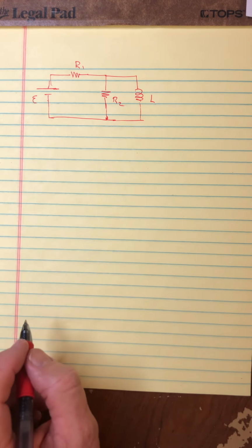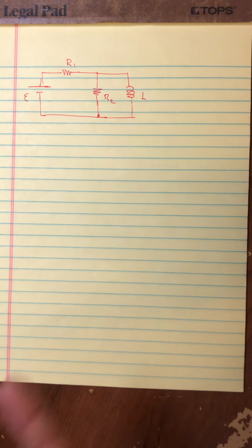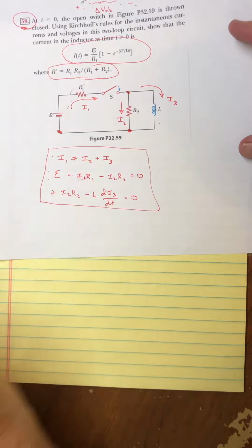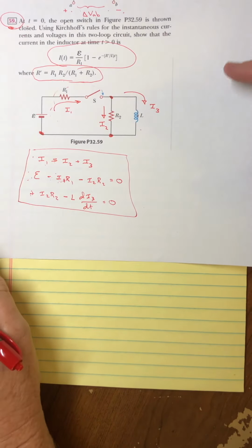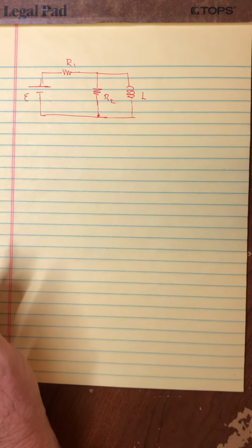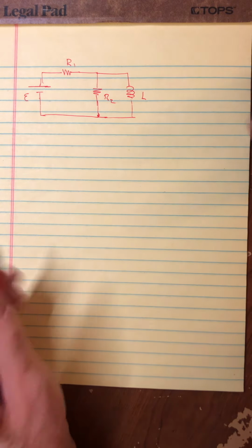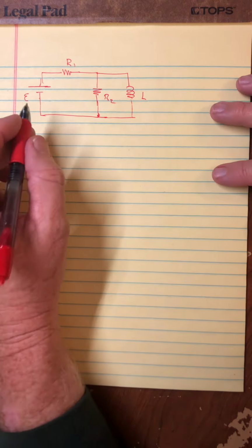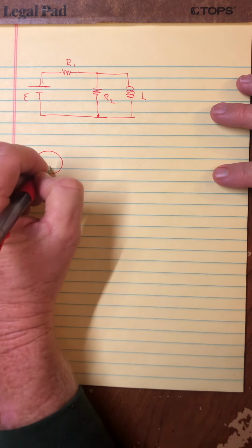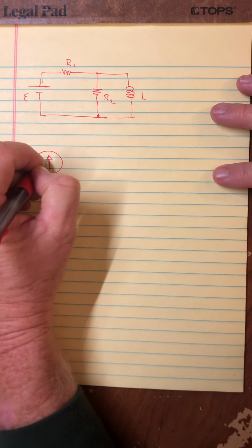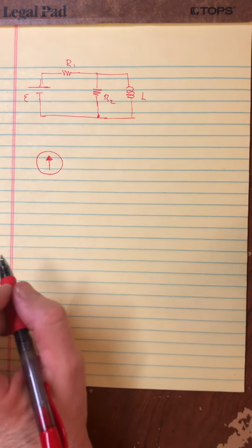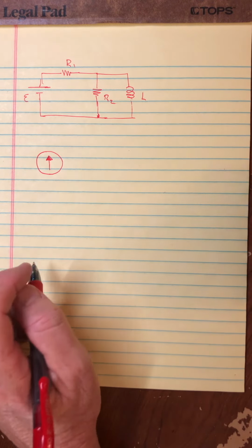It's neither. You kind of feel stuck and need to go back to doing Kirchhoff's laws that we talked about. And technically you are stuck, although here's what's nice about a source transformation. For those of you who know what I'm talking about, you can replace a constant voltage source with a constant current source.